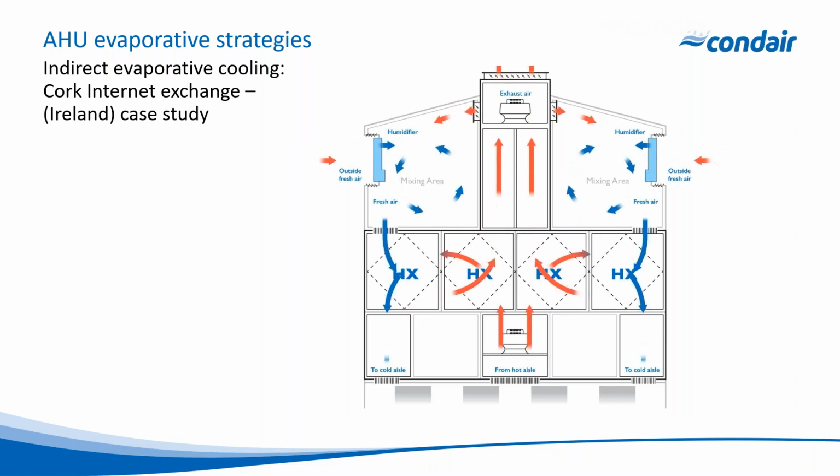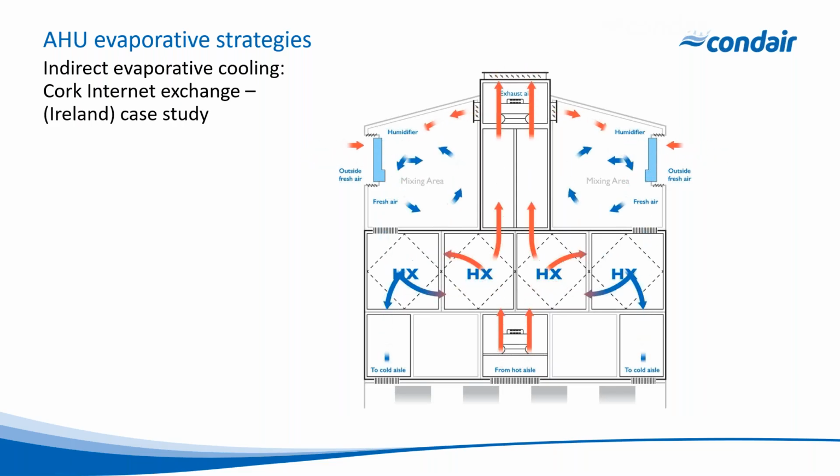So again, just like having a cooling coil, we're taking warm air, cooling it sensibly and putting it back into the space. Only in this case, we're using an evaporatively cooled heat exchanger instead of a chilled water coil.